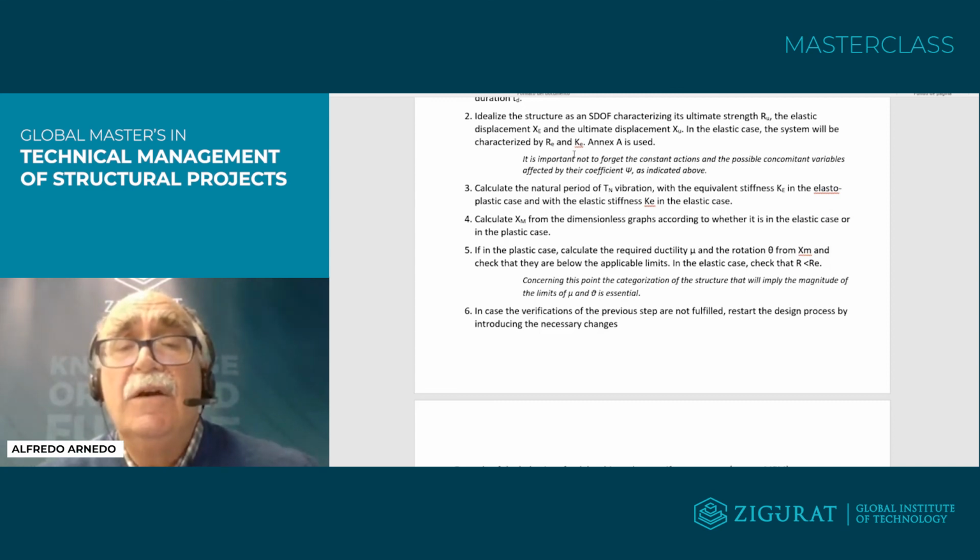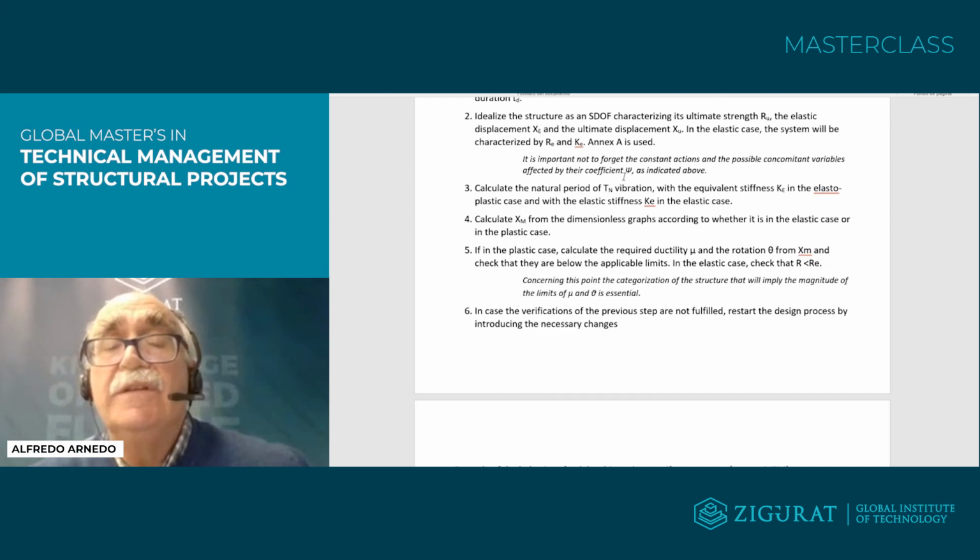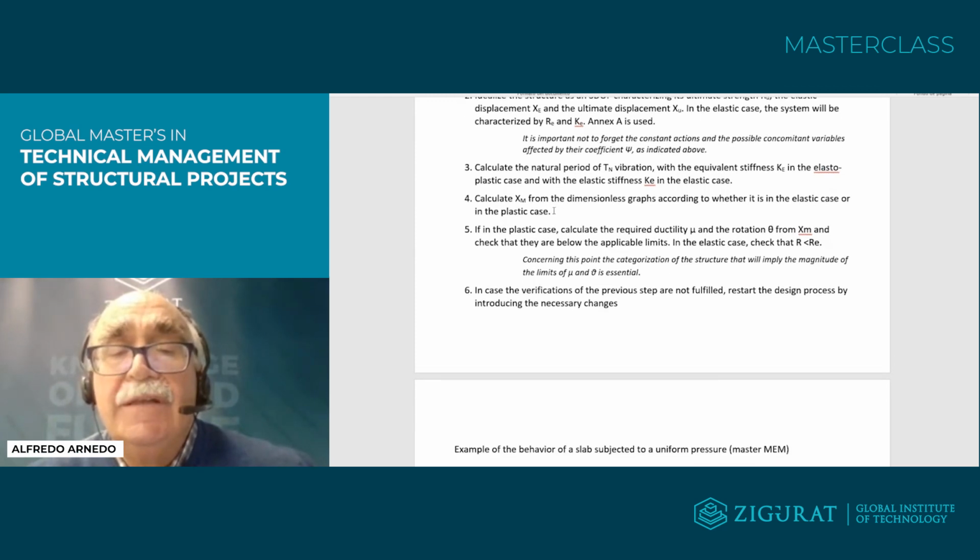Obtaining the mass and stiffness, and taking from these the period, and comparing the load duration with the period, and comparing the maximum displacement that we reach by direct formulas or by the graphic, and being sure that we are within the limit of ductility that copes with the standard.